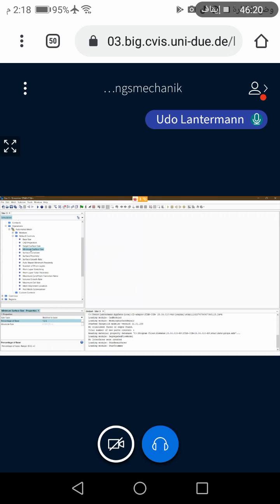The next ones will be the default ones. Curvature, the default one is 36. That means 36 points over a circle will be discretized, so for 360 degrees we use 36 points, and the distance between 2 points is an angle of 10 degrees. But for our case, it's fine. Surface proximity, we also use the default one. Surface growth rate, we also choose the default one, it's 1.3. Curvature repair is also default.